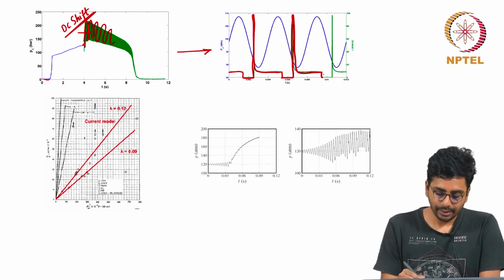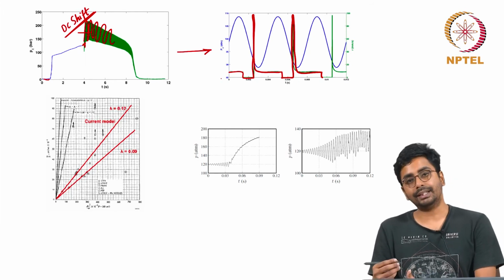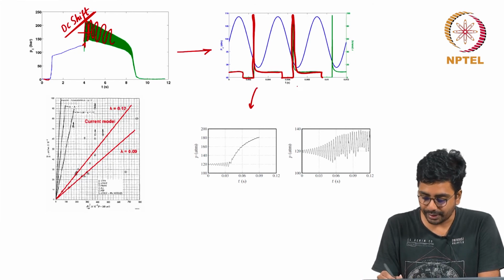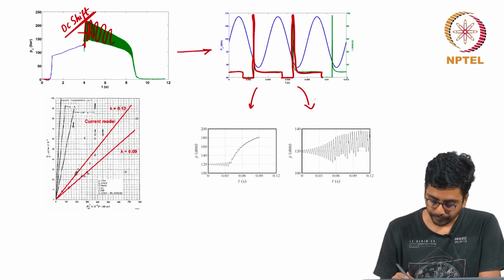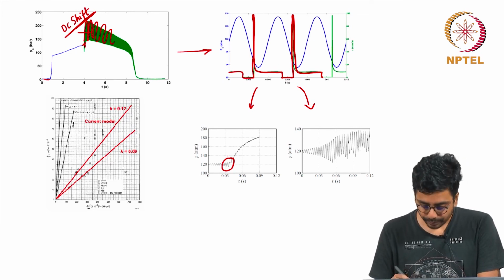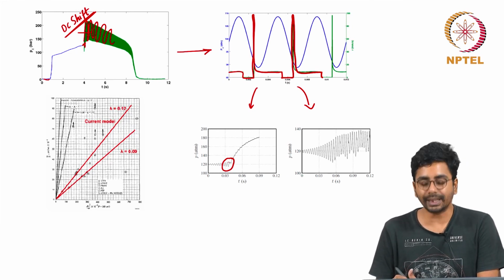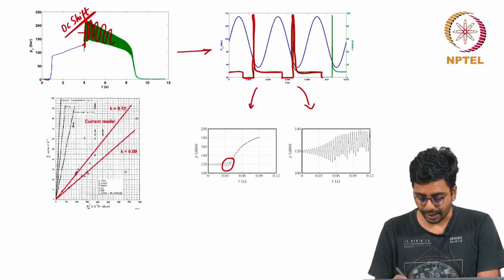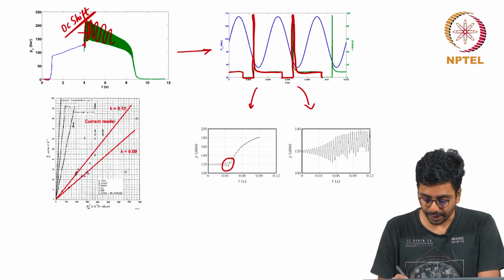The origin of DC shift was conclusively shown using CFD calculations, where after linear or exponential growth of oscillations, when a critical amplitude is crossed and the depressurization rates have crossed the critical value, the propellant undergoes extinction reignition cycles leading to DC shift.